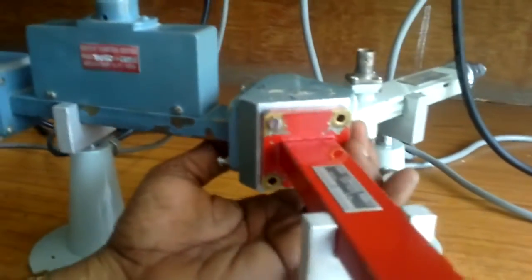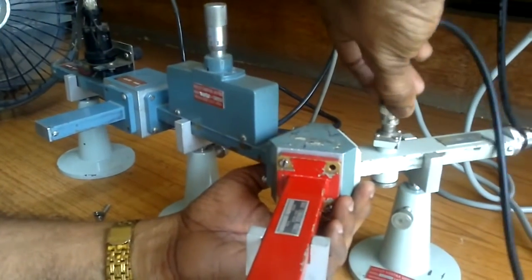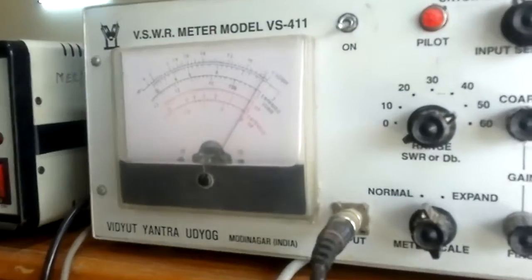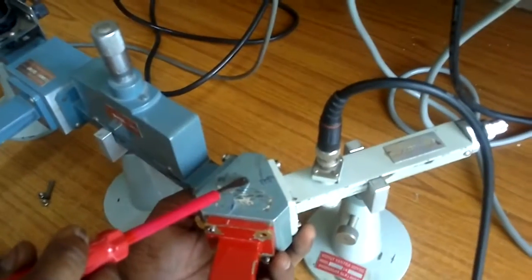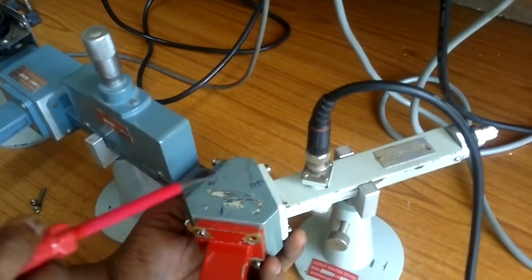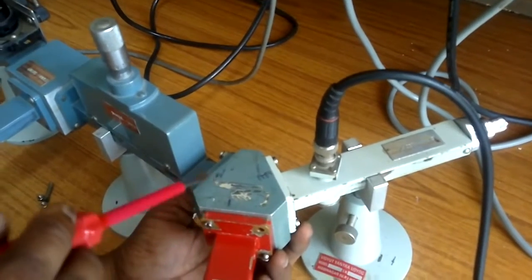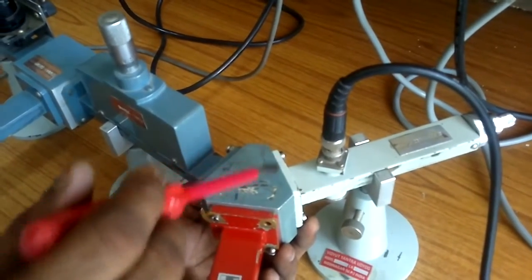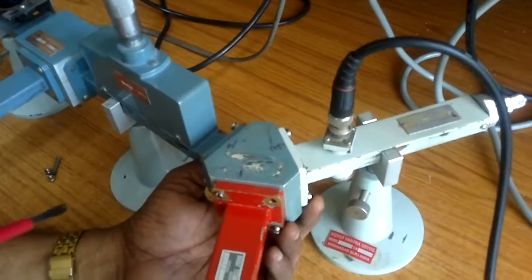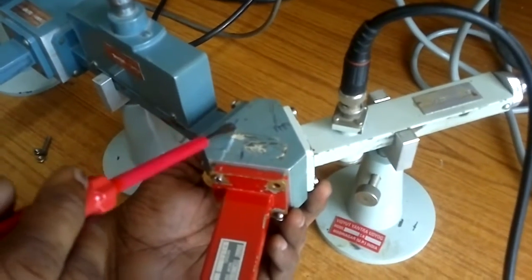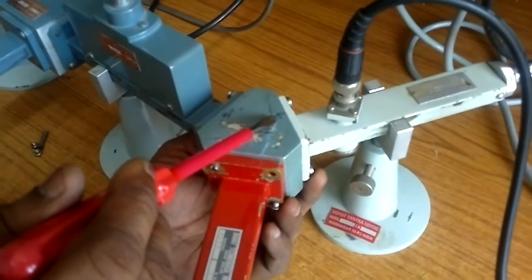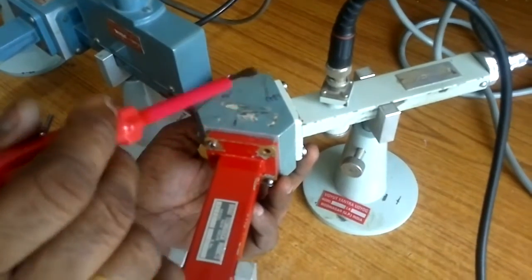You fix it properly without any gap, and you connect the BNC towards the port 3, your detector mount. Now port 2 as an input, port 3 as an output. Actually power goes from 1 to 2, 2 to 3, 3 to 1. These are all reading in ideal condition 0. Now our input is 2, our output at 3. According to your ideal condition reading, you are supposed to get 0. Same reading you are observing.